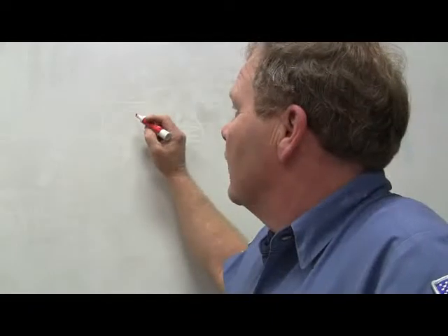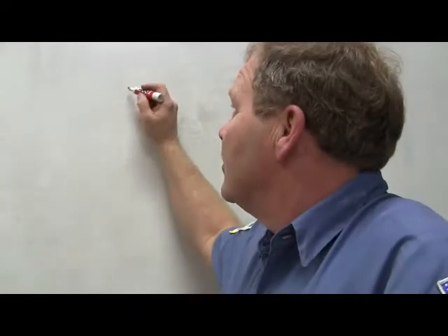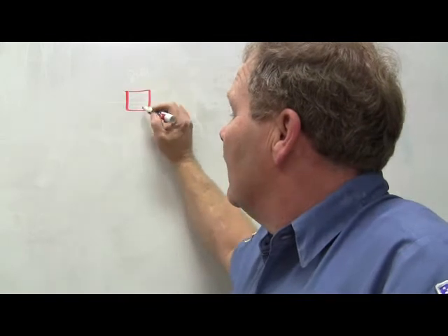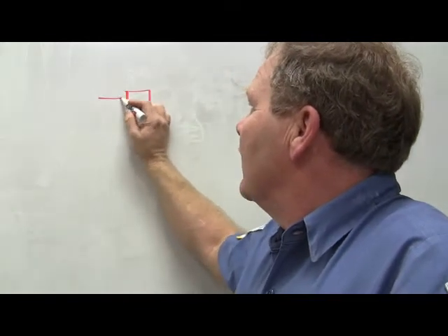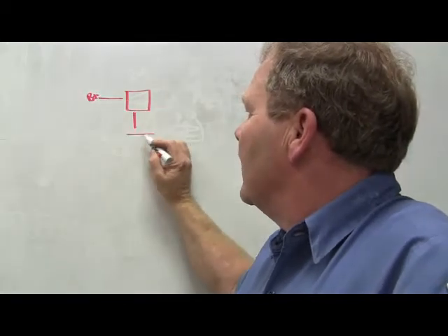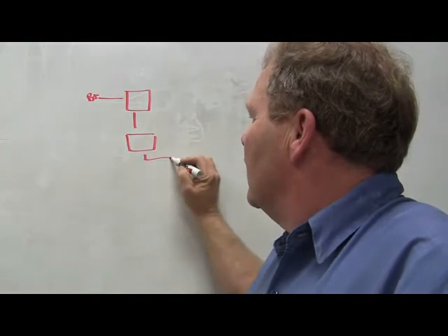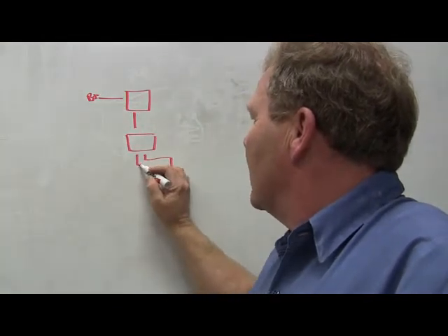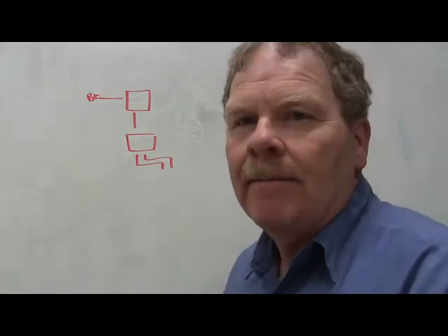All right, the relay controlled headlight is a light duty device which activates a heavy current relay. That's number 7, right? That's true. Let me ask you this. Say you've got a headlight switch right here, and that headlight switch has B plus coming in. Coming out of it, it goes through the dimmer switch to the lights, and the dimmer switch switches from bright to dim. You got me?